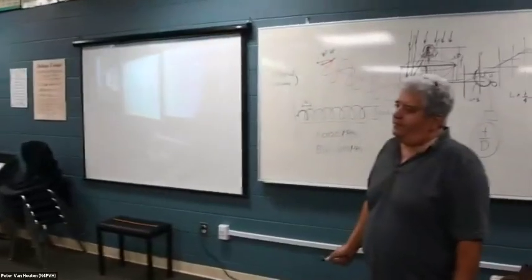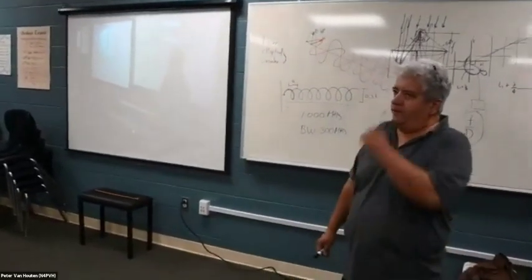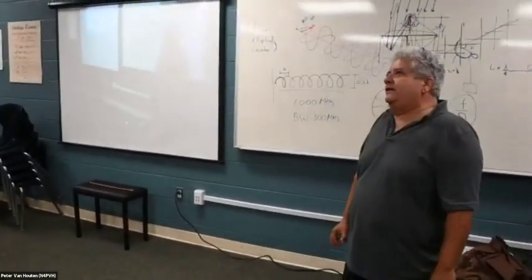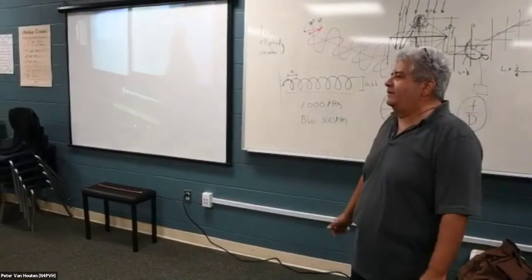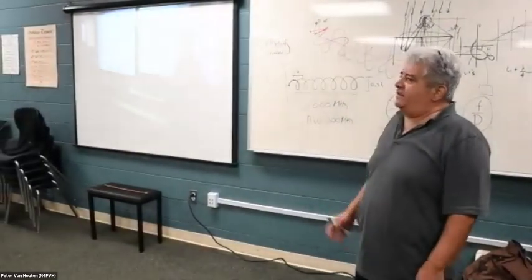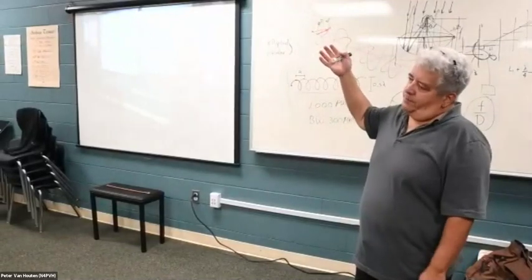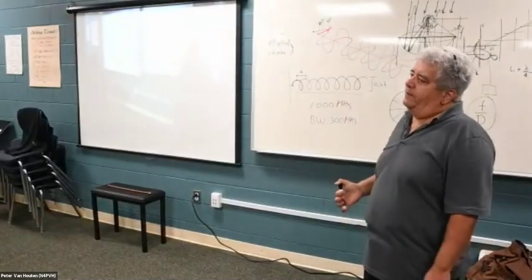There are conventions for this. And I was reading about it, and I know that you need, for example, for 23 centimeters, 1300 megahertz, a dish that is a minimum of 10 feet in diameter. And the same dish can work on the next higher band, which is 2.4 gigahertz.